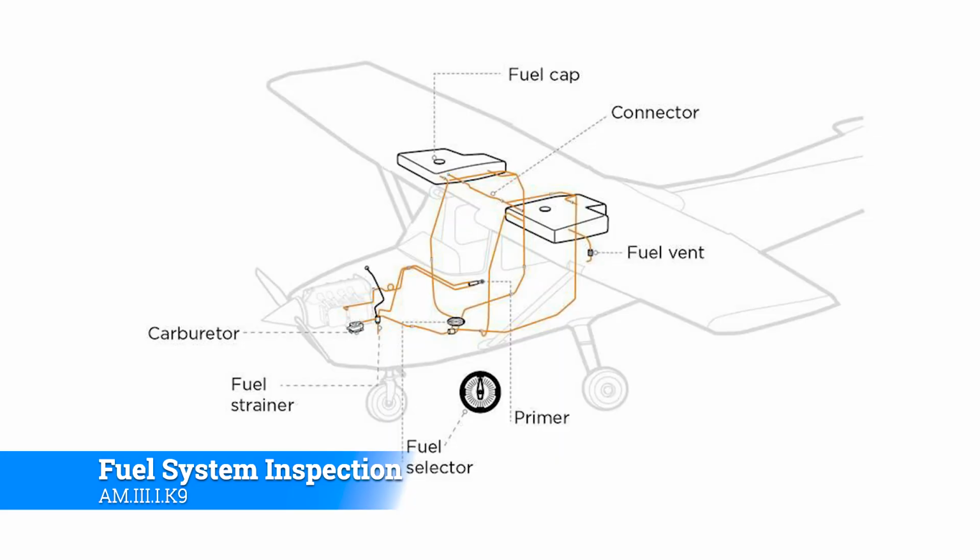Okay, so if we're going to inspect the entire system, we're going to always be looking for wear, damage, and leaks. Leaks being the big thing. Fuel leaks are not a good thing on an airplane whatsoever because fuel leaks lead to fire, especially when we're talking about big bleed air systems that are at play. Those fuel leaks can easily start a fire locally that then just basically cascades throughout the rest of the plane. So you do not want to have a leak anywhere.